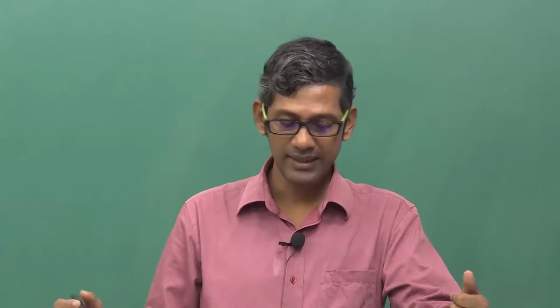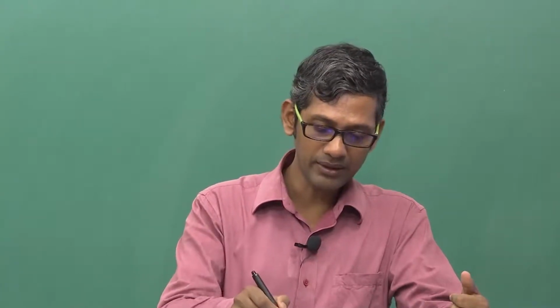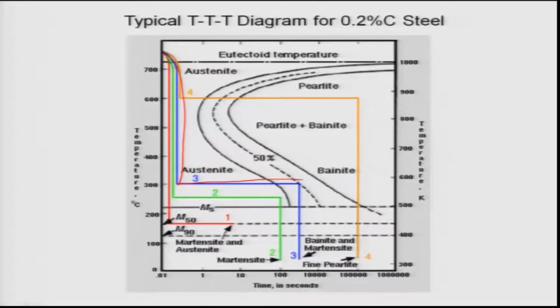This is one such. So, one can also have a diagram like that, you can cool it like this, keep it a little longer and quench it. By doing that, in this case 5, I can transform more austenite to bainite, and then the remaining, maybe a certain fraction, 10 or 15%, will be transformed to martensite by cooling. Okay, that is one other way.